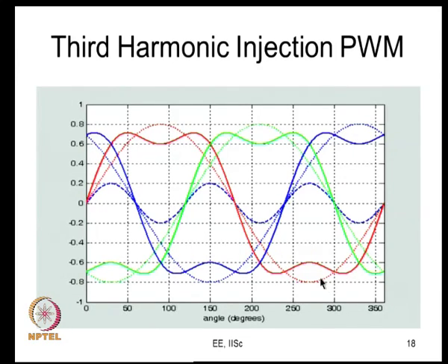It is the same nature of curve. Here 0 becomes 0.5, that is essentially the difference, and this is 0, 0.5 and 1. You just change the scale and draw, and now this MR star will give you the duty ratio. So, you can calculate the duty ratio. Once you calculate the duty ratio, it is possible for you to calculate the conduction losses.